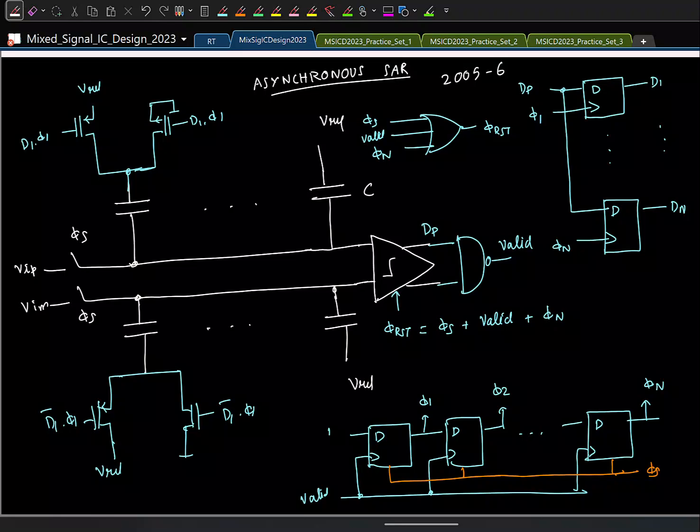Great. So this is basically almost a digital thing. So it has only dynamic power consumption. It scales easily. So all the advantages you see in the first paragraph of a digital IC textbook will all be valid for a SAR ADC also.